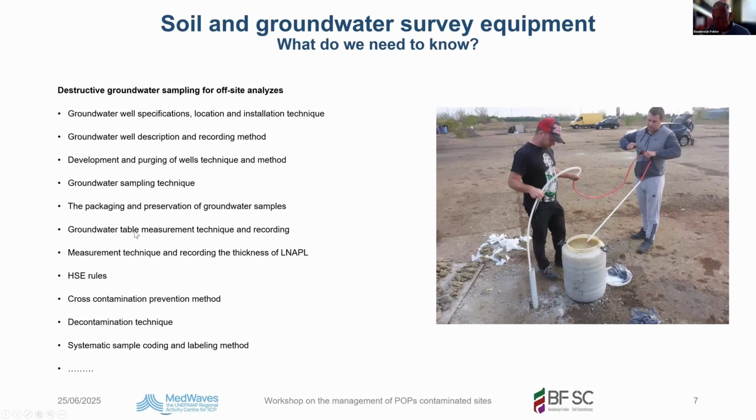Then you need to know the groundwater table measurement techniques and how to record. The measurement techniques and recording of the thickness of an LNAPL. I discussed that, the LNAPL: light non-aqueous phase liquids, for instance the oil, the floating layer. You saw that in the cross-section this morning.